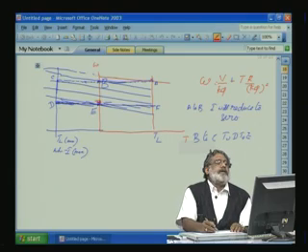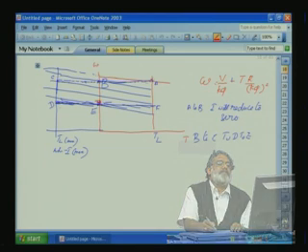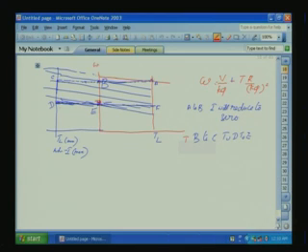Last class we were talking about how to control the speed of a separately excited motor with the 4 quadrant operation. So, if you see here, this is the torque speed characteristics. We will control the armature voltage V such that the current will quickly come to 0 from A to B. A to B, as far as the speed is concerned, is the same speed, a parallel line with respect to TL with the x axis.